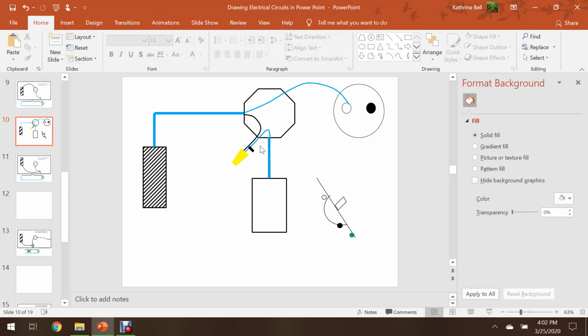So I've got my ungrounded conductor, black insulated, connected to a white re-identified with black tape conductor that's going to come down and go to a terminal on my switch. This switch terminal should be brass colored here instead of that open, but that's okay. You get the idea. We've got a single pole switch with two terminals.